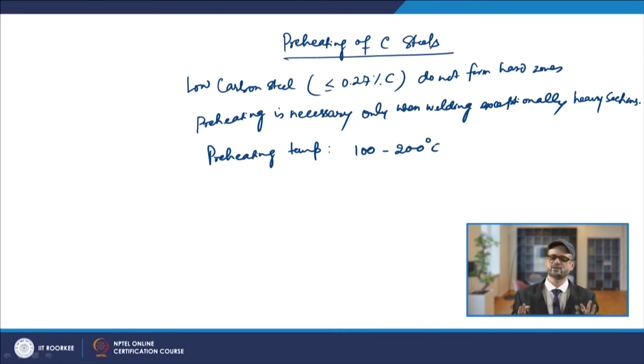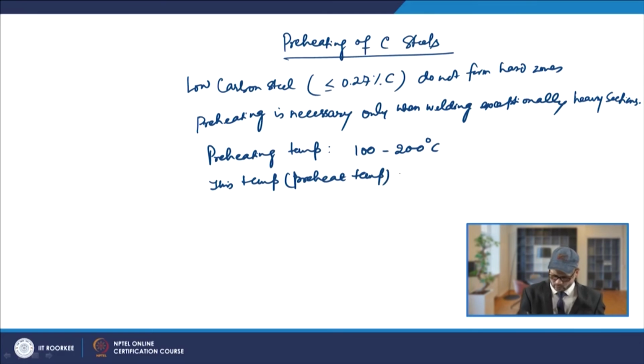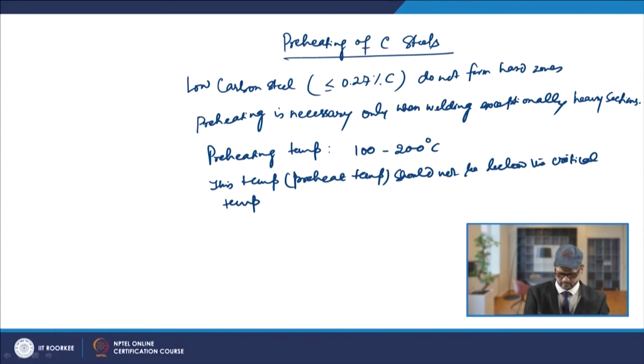But then there is another thing: this preheat temperature should not be below the critical temperature for the transition from ductile to brittle behavior.